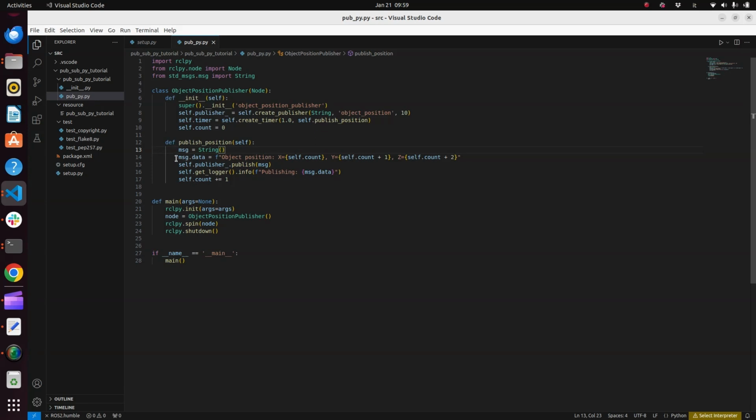And then basically you need to check the raw definition of your message that you want to publish, and in this case it's going to be data. And then since that is going to be a string, you need to publish a string. Okay, and then actually you publish by typing publish. Okay, and this node could stop here.